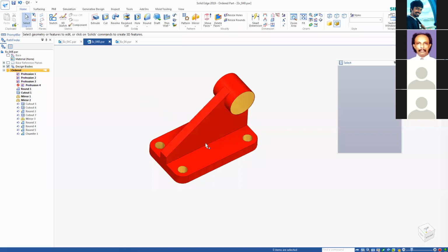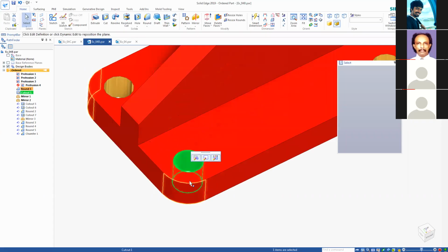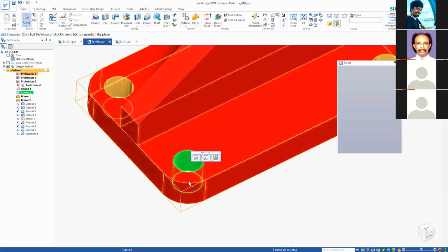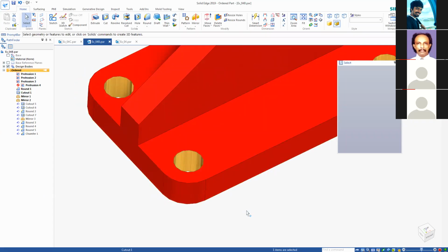Now, if you see this, for example, the fillet is over there, and then the cut out, the hole, is after that. What I have done is use the center of the fillet, or this corner, as the center of the hole. Remember, this is not small, this is slightly big. So you cannot consider this one a cosmetic feature.